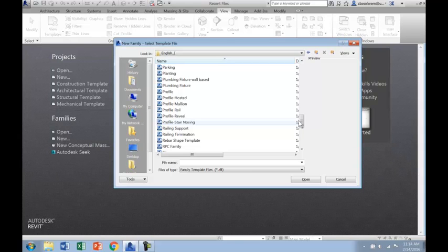That's going to apply obviously to mullions as we've been using them, but also to handrails, to stair profiles, to slab conditions where a slab turn down happens with a flooring system, to roof elements, to soffits. Pretty much everything you can imagine is dealt with using profiles that then are extruded. Just like when we were making conceptual masses, it just happens at the detail level rather than at the building level. We're going to start here with just the dumb profile, the profile template.